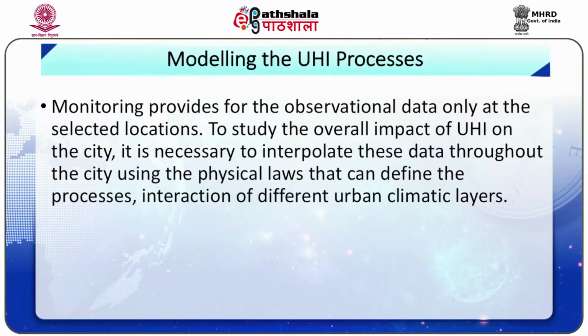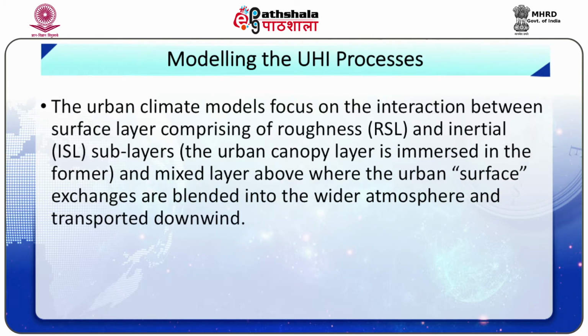Now, the second way to look at the urban heat island is through modeling. Since monitoring provides observational data only at selected locations, to study the overall effect of urban heat island on the city, it is necessary to interpolate these data throughout the city using the physical laws that can define the processes and interactions of different urban climate layers. This task is accomplished through computer simulation and modeling.